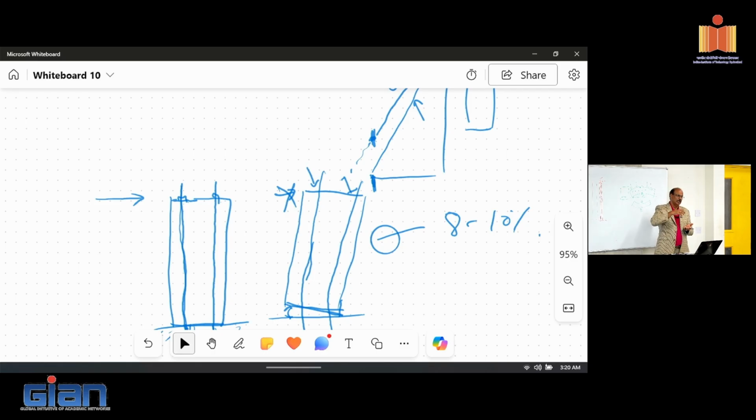So the question is, if I built this and shake it, how long does it take to settle? What we found was if I put in 8 to 10% damping, my displacement went up by about 10%. The shaking lasted another 10%. Can the structure sustain that? This system, everything is elastic. Why can't it sustain something like that?